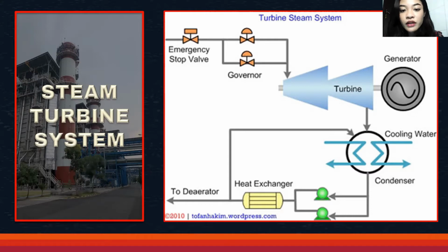This steam will be condensed by a surface condenser after the steam turbine. Condensation will rapidly occur at lower pressure. To achieve the right condition, an ejector is equipment after the condenser to improve vacuum pressure. Finally, the condensate will be pumped to the boiler, deaerator, or water tank and continue the Rankine cycle.